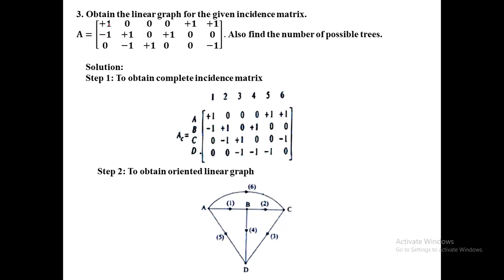First we check +1, -1, 0, then -1, +1, 0. Next column: +1, there is no -1 value. Here we got the answer +1. We can say that this is the reduced incidence matrix because we can't get the 0 value in this third